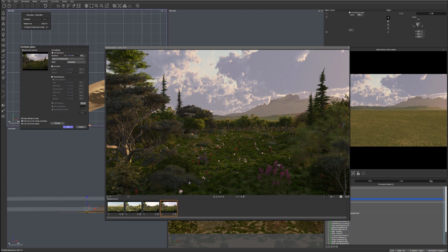Again, I probably will continue working on this image later. I will rework the sky. And by the way, a tip on the sky, what I usually do is set up a rough shape for this and play just with atmospheres, nothing else. And when you create a beautiful looking atmosphere with the sky at one specific height, just save this atmosphere, save it with specific information so you know what it is applied to. And after that from your library you can easily pull it out without worrying. And you saw how sometimes it's slow reacting, so you can avoid this by creating separate atmospheres and importing or loading them afterwards.